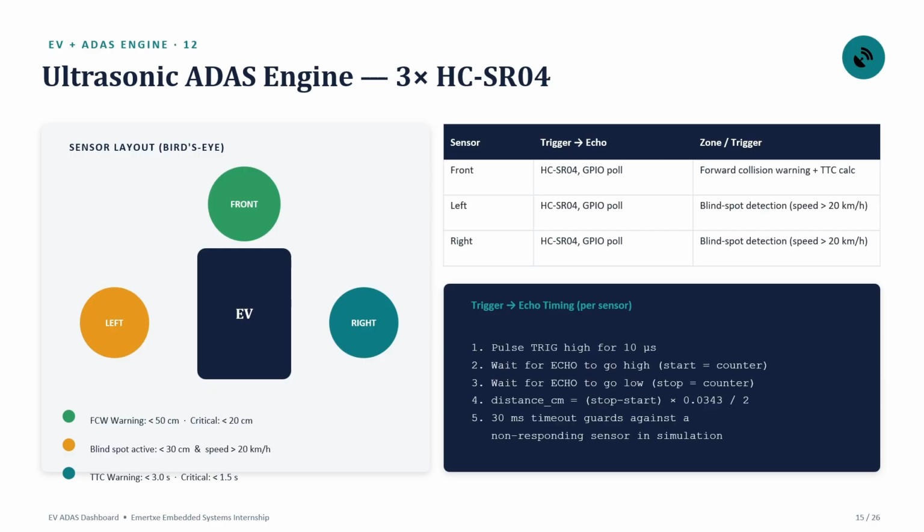Like we can see here the world view, or it's also given in the simulation. The ADAS uses three ultrasonic sensors, one in the front and two on the side, left and right. These three ultrasonic sensors are used in three different